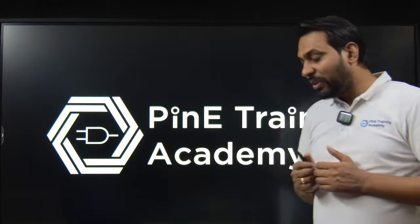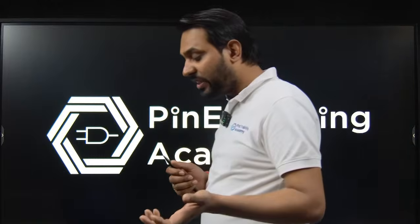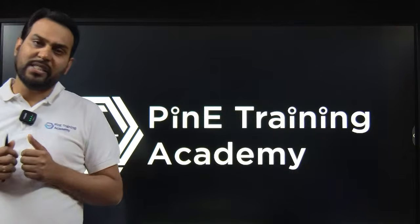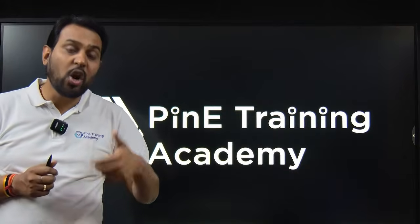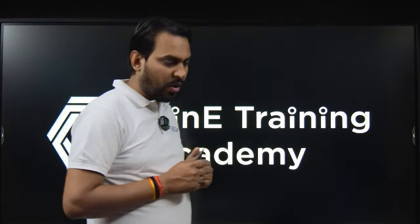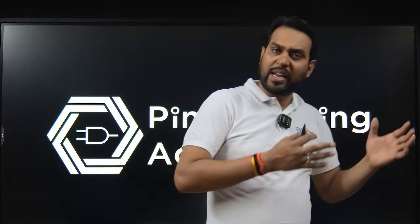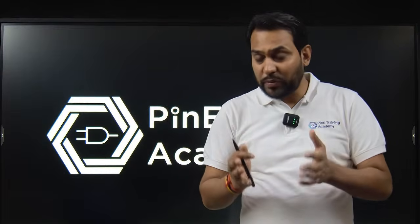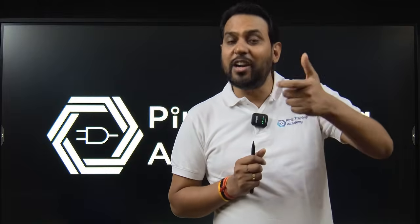In the second class we started, okay, we have a resistance, we have a capacitance, but now let's talk about the physical resistance. You have a fixed resistance, or you have a resistance created by design using the MOSFET. A MOSFET has different regions: cutoff, linear, saturation, and threshold. If you use a MOSFET in the linear or triode region, it behaves like a resistor. So you can use it as a voltage controlled resistor.